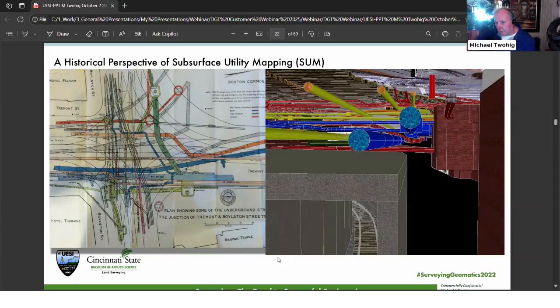So we were actually profiling the roof of the tunnel, and then further investigation with vac trucks to get the exact depths for profiling and depth of cover for the new pipes and keeping the separation they were looking for. As a follow-up question to that, how accurate were the depths that you saw in the GPR information compared to when you actually excavated? Well, on the tunnel itself, it wasn't spectacular, but we believe that was because of the soil and the number of utility crossings.